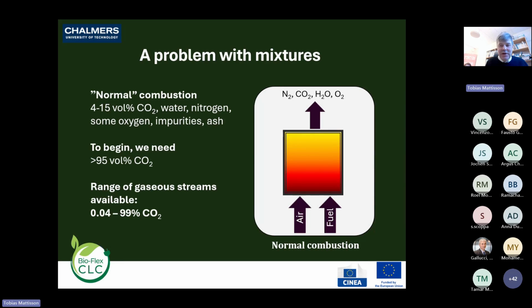What you need in order to use it is often to have it in very concentrated form. So a lot of the challenge with CCS through the years is to go from 5 to 20% to pure CO2. Everybody knows that this is not done for free, because if you need gas separation, then you will have a thermodynamic work in order to obtain this. You can never go beyond this, as far as I know at least.